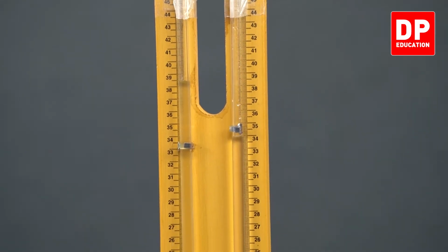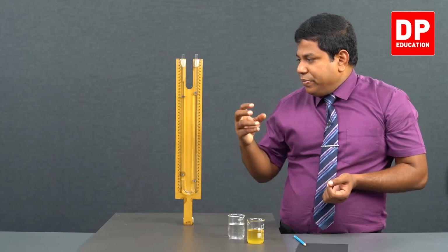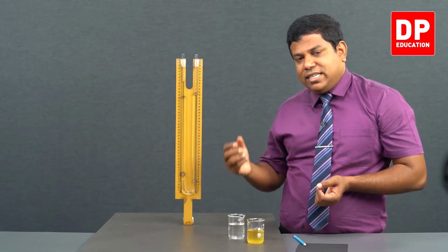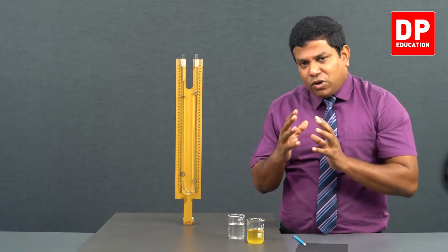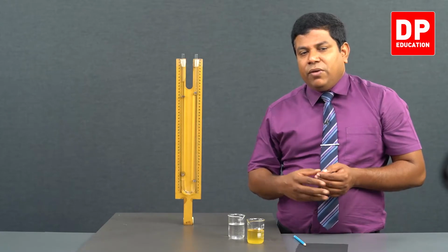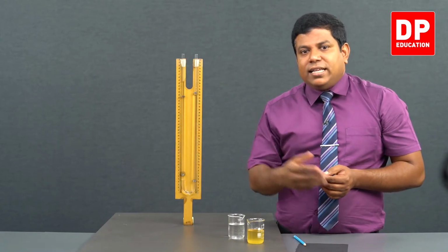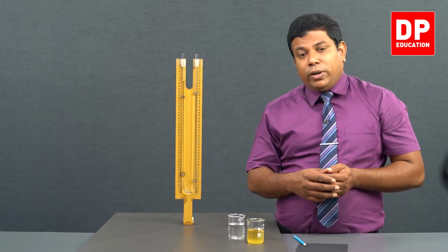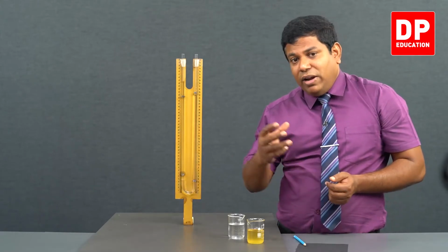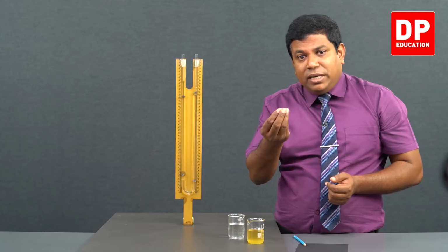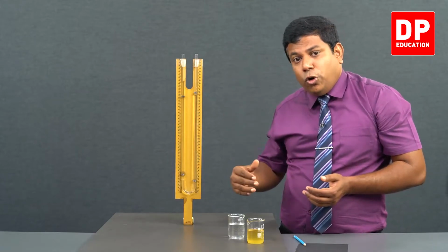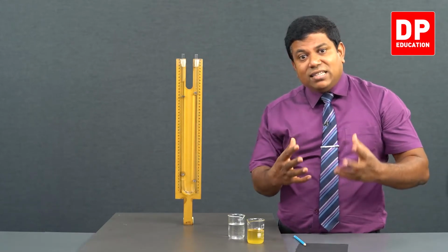A couple of restrictions we have here. One, the density of both liquids, that means the water's density and the other liquid's density, must be somewhat close to each other. If we are using water and mercury, what will happen? If water is at 1000, we know mercury's density is 13,500. You will get a 13.5 times difference. The relative density will be 13.5. Then to raise the mercury by 1 centimeter, you will have to put 13.5 centimeters of water. Then the height of this U-tube will not be enough to get 5 different readings and draw a graph.